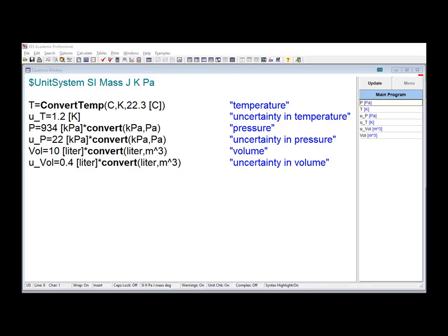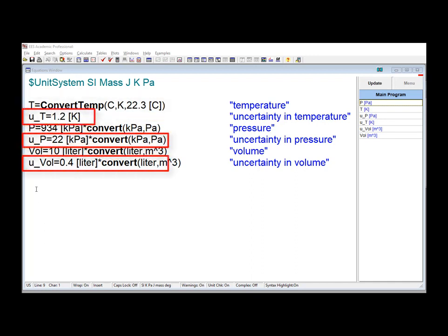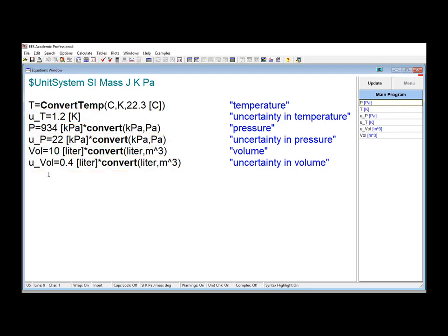So we'll put all these inputs into ease, and these include both the measurements as well as the uncertainties. We're going to assume here that argon behaves as an ideal gas, which we don't have to. We could also use the internal property routines in ease. But if we assume it behaves as an ideal gas, then we can obtain the ideal gas constant as the ratio of the universal gas constant to the molar mass of argon. And then we'll compute the specific volume with the ideal gas law. And then finally we can compute the total mass of argon in the tank according to this equation.